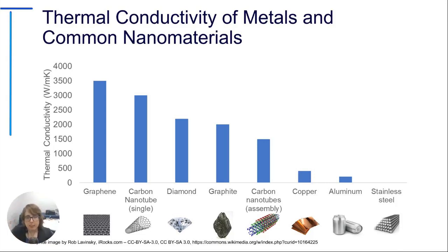And stainless steel is actually more thermally conductive than most non-metals out there, and actually even more thermally conductive than a substantial number of metals. But its thermal conductivity is around about, depending on the grade, between about 11 to 20 watts per meter Kelvin. And as you can see on this chart, that's low enough that it doesn't even really register on the chart.